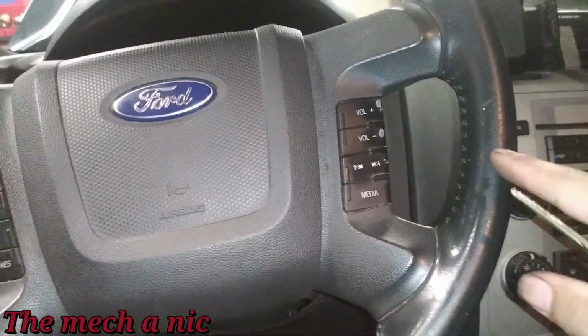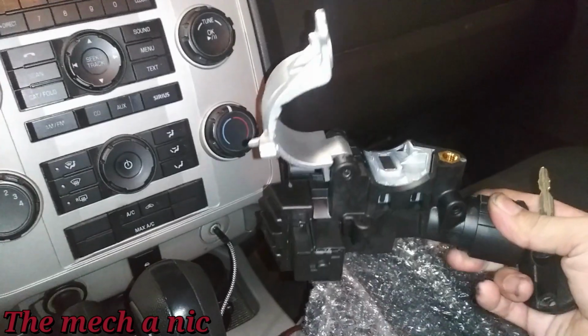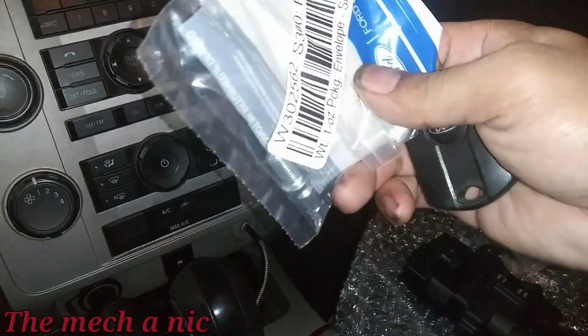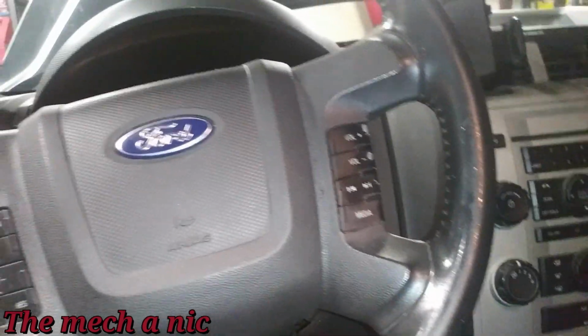So what's super common on these Ford Escapes is the ignition switch housing to go bad. So that would be this part right here. And we have a OEM Ford part to replace it with. And whenever you replace this, you want to make sure you replace the shear bolt. So here you can see I got another OEM part right here. So that's what I'm going to do tonight. I'm going to go ahead and get this part installed.